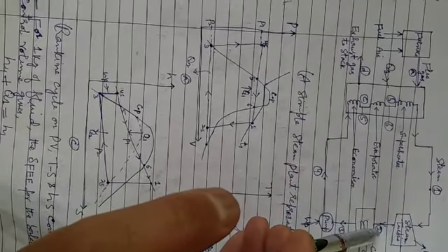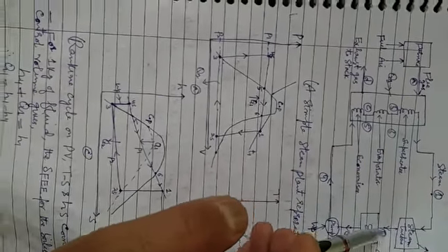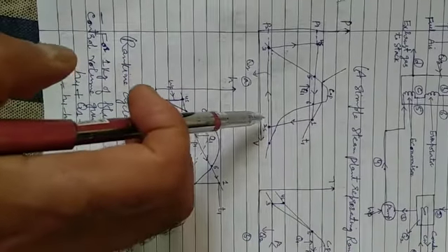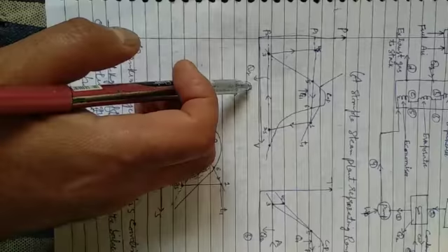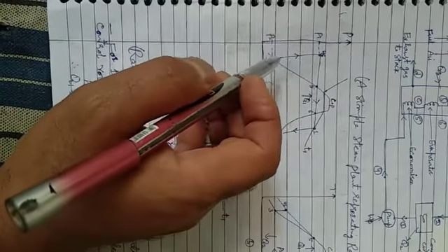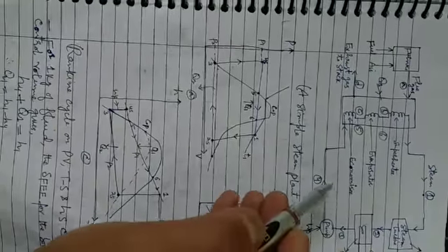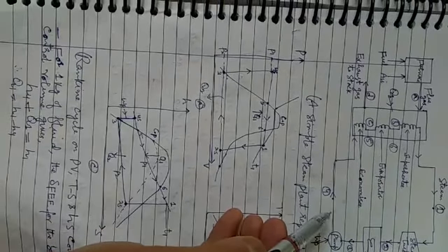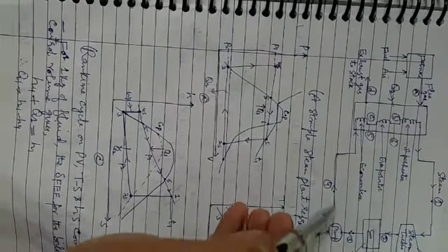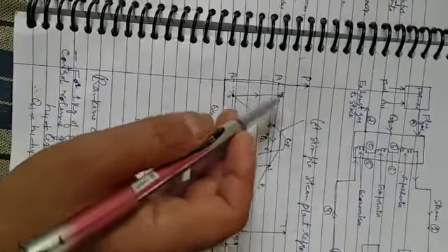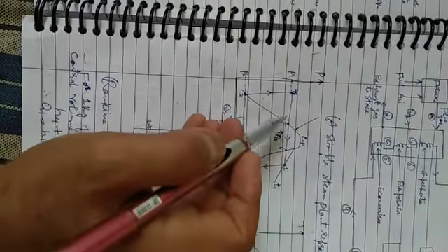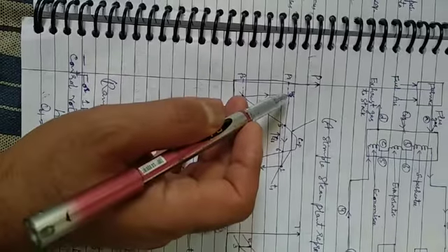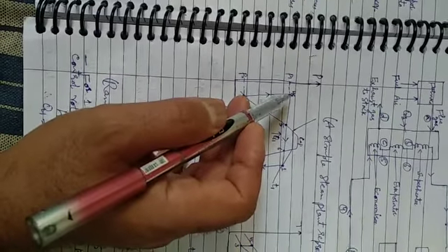It is the isentropic expansion process, 1 to 2. There is work done by the steam. Then 2 to 3 is the condensation process, where heat is rejected. Then 3 to 4 is the isentropic compression process. That is work done by the pump. Then 4 to 1 is the heat addition process. It is the process of the boiler.